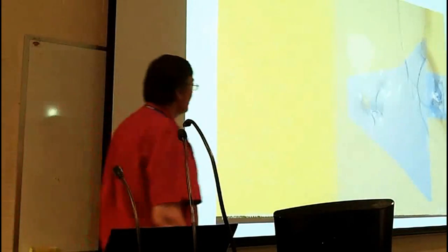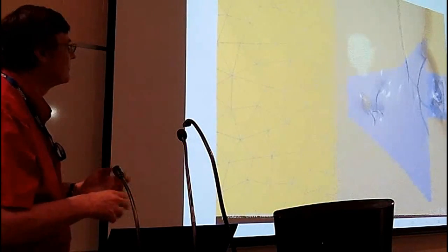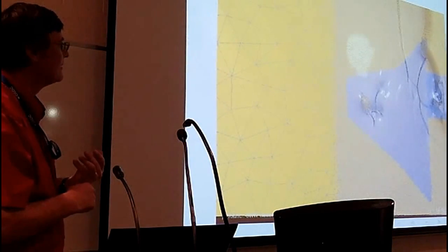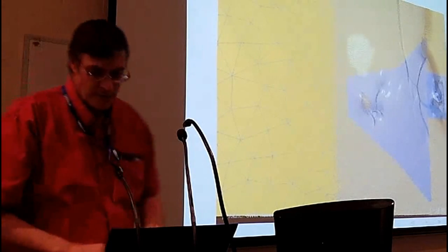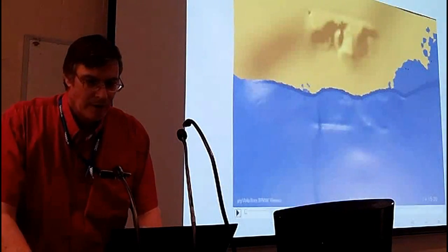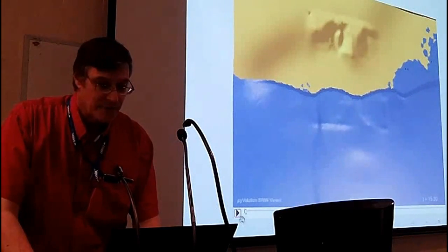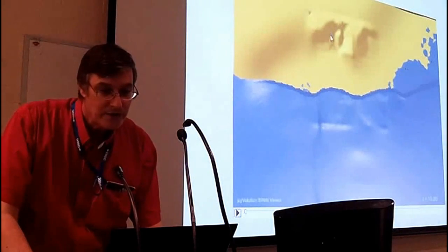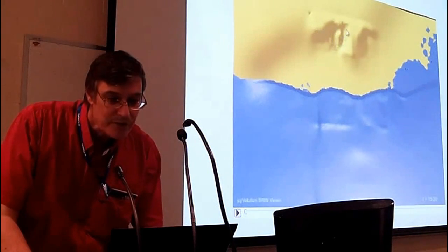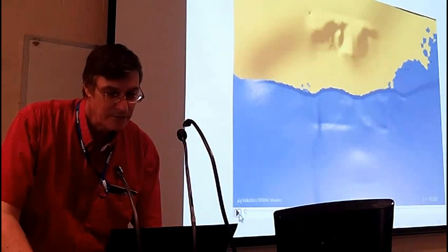Here's a grid for this problem. We have a fairly coarse grid out there. We're interested in here, so we have a very reasonably fine grid. This is actually a static grid. It's not dynamic. We basically choose where we're interested in and then refine in those areas. So this is our simulation of that area, and it's going to, not quite sure, it's up one of these valleys that it's going to be amplified.